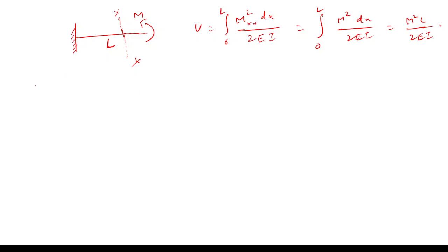So can you find out the strain energy for this? This beam is of length L. First, you have to find out the bending moment at any particular cross section, and then you have to proceed for strain energy calculation. Okay, that is the procedure.